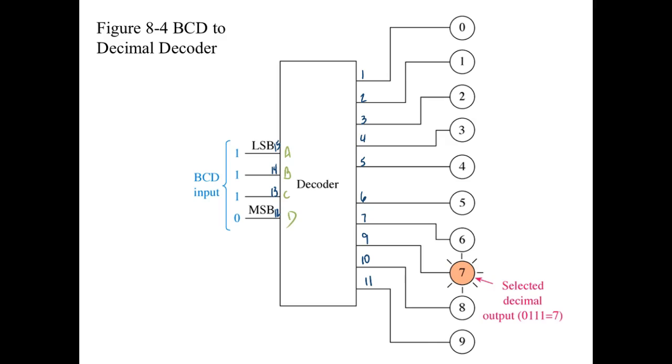Yeah, but normally on the schematics, they don't draw the power pins. They take for granted, if you understand digital, you understand nothing works without power applied. This gives people problems sometimes because they'll wire up a circuit, don't hook up power, and wonder why it doesn't work. But they don't understand that the power pins are a given, right?